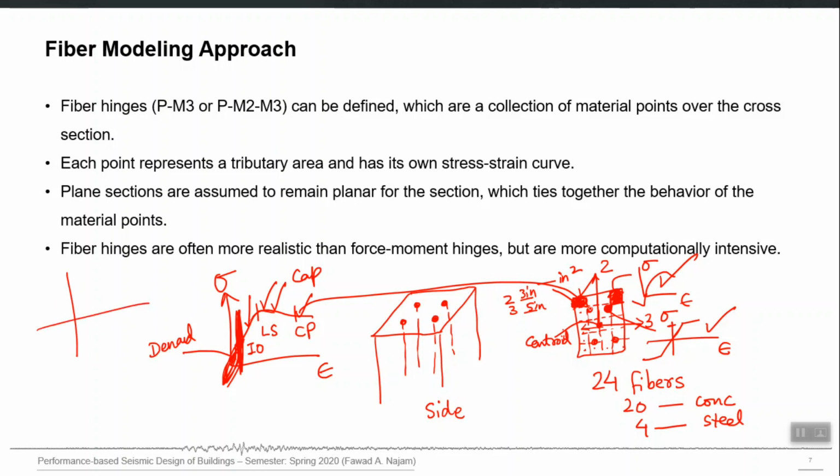Let's say here was a steel bar, rebar, and I have given this stress strain curve to my rebar. After the analysis I come to know that my applied loading will stress this particular rebar, this particular fiber, up till this level, right? So I should exactly know that this bar will be yielded as a result of this applied loading.